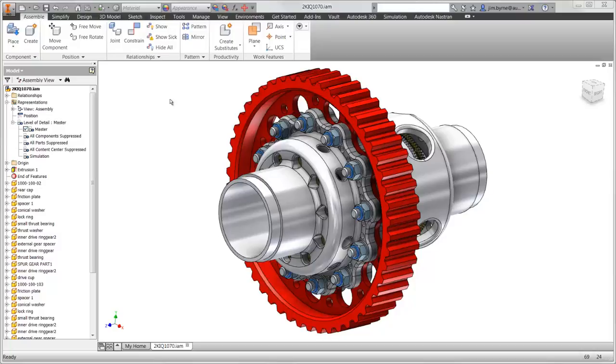Taking a close look at the design, we have several bolts, nuts, and washers being used to fasten the components in the assembly. There are a couple approaches that can be taken to set this analysis up. First, we can analyze the bolts as they are and gain some knowledge of the stresses on each of them. The second approach is the use of connectors. Connectors act as one-beam elements, which solve extremely fast, and they also provide additional information for the shear and axial force. Now that we know the setup we're going to use, we can hide the other parts in the assembly,